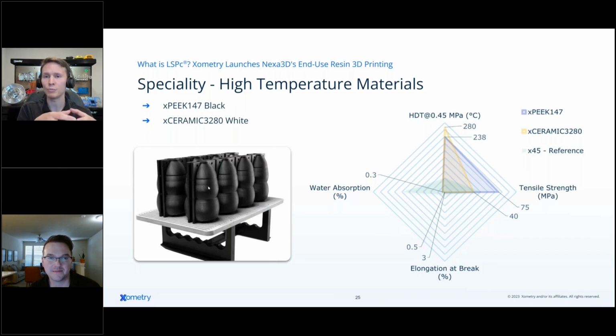They have kind of self-supporting, self-strengthening features to it. So when you're working in those environments, just know that any flex can lead to a break. So it's very different than the polypropylene, where its chemistry is to flex, but you do get that high heat deflection. So very good for tooling inserts and other jigs and other high heat applications. But just be mindful of that in your design stage.